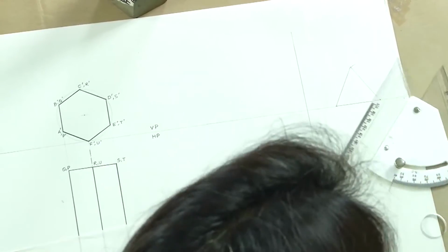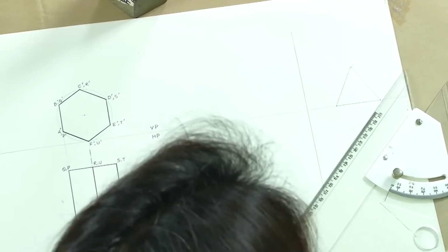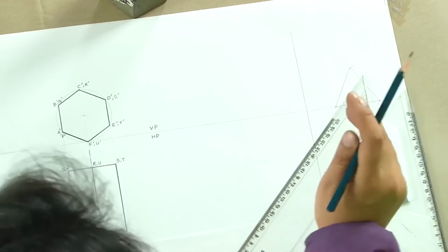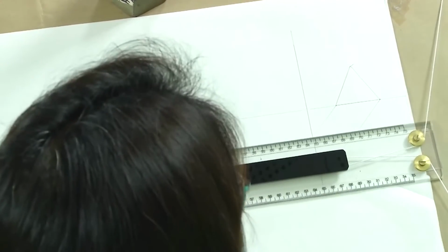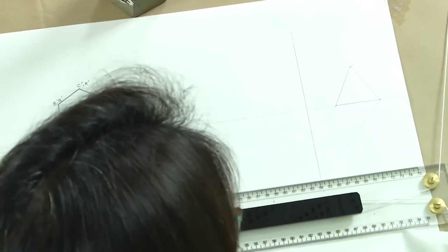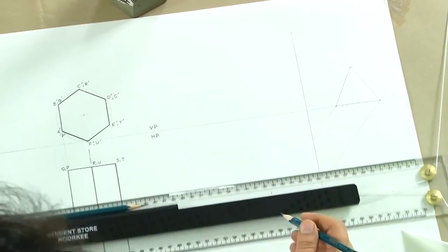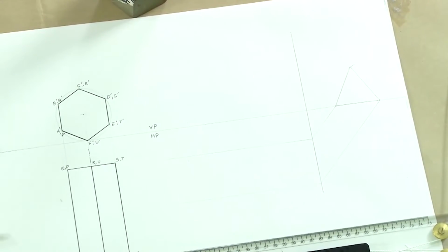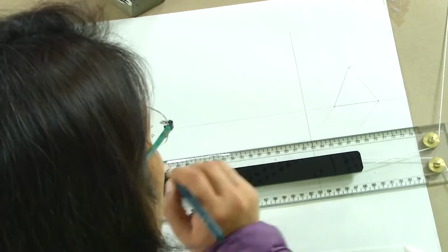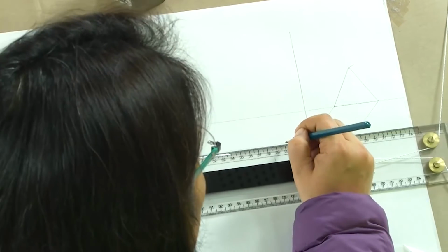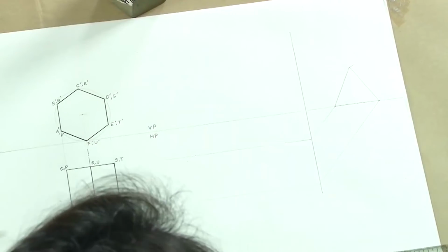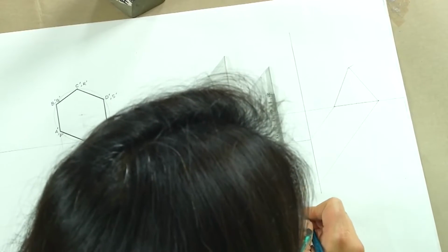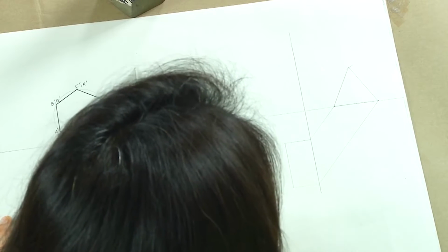So, just like as we did, we will take it in reverse. We are taking it back onto the HP. And what we see in HP, since the axis is parallel to HP, is the true height of the solid. Assuming that the height of the prism is 10 centimeters, taking 10 centimeters here, what we see is a rectangle like this.